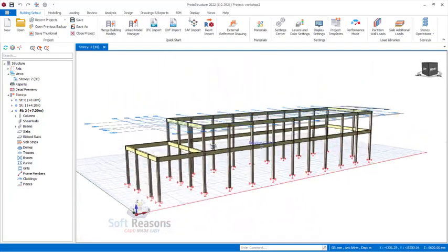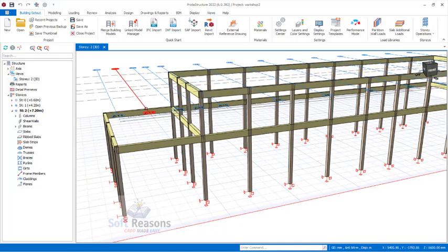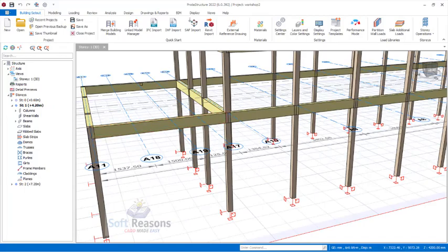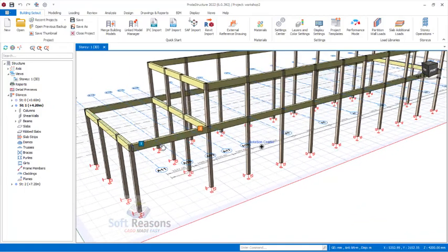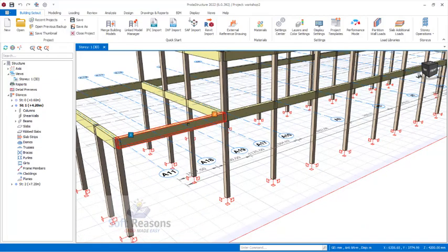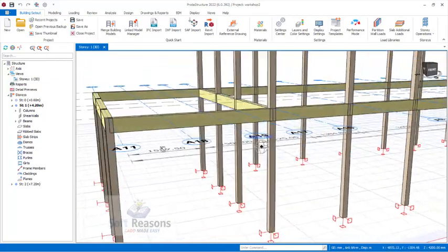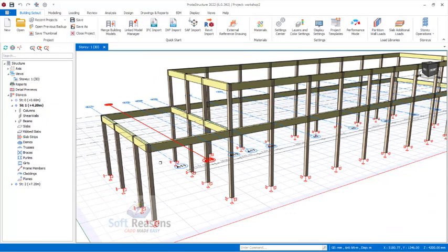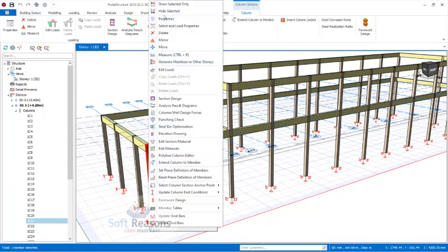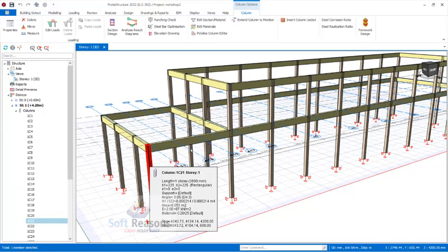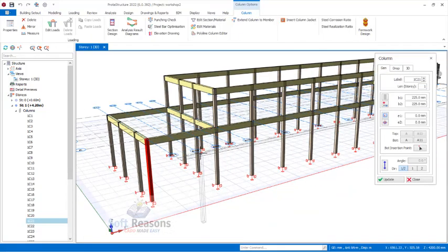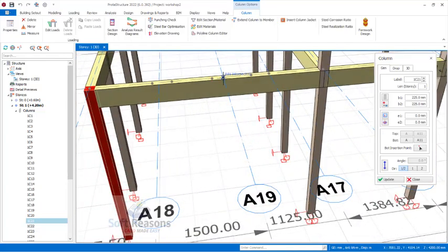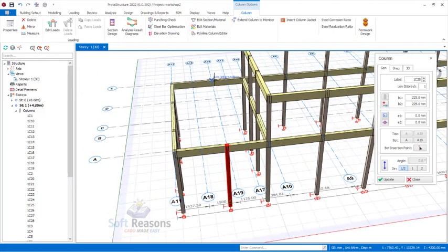What we now need to do is introduce some columns. One more column. So move the gray line to level 1. We need the columns here, because we are using steel trusses and we want to sit the trusses directly on the reinforced concrete beam, which should be on top of the reinforced concrete columns. So for us to do that, select this column, right click and click on property, and once it is activated, move closely and place it correctly at the green line intersections to have that placed successfully, just like this.